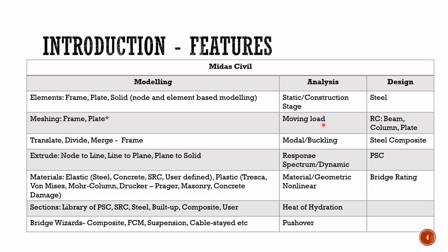Further, for slender geometries, we have modal and buckling analysis for simulating the seismic events and the dynamic effect of the pedestrian and vehicular load. We have the response spectrum and the dynamic analysis in MIDAS Civil. For slender geometries, we can perform the nonlinear geometric analysis and nonlinear material analysis. Further, for mass concrete structures, MIDAS Civil offers heat of hydration analysis.